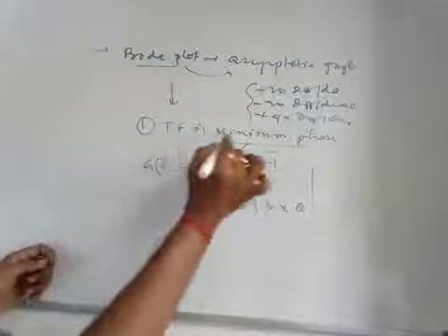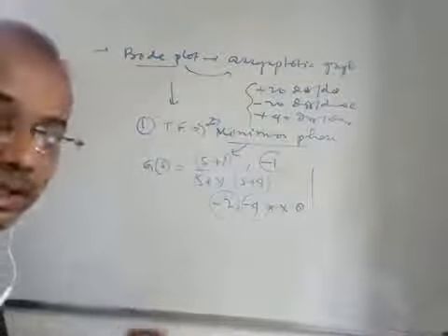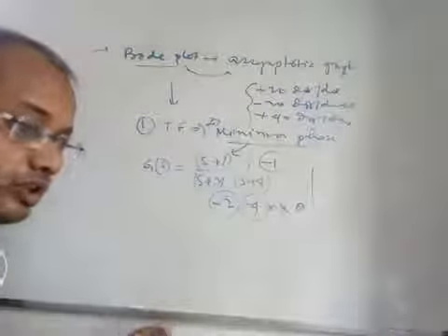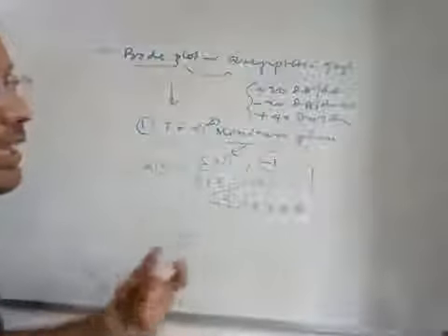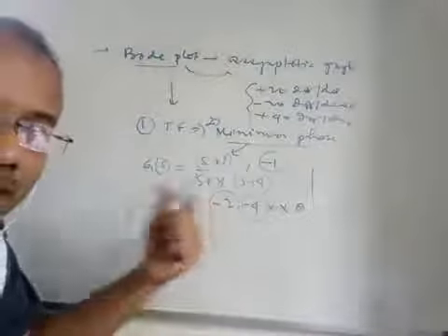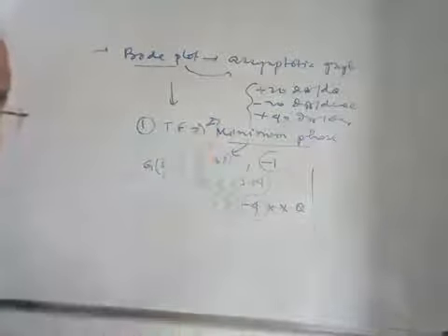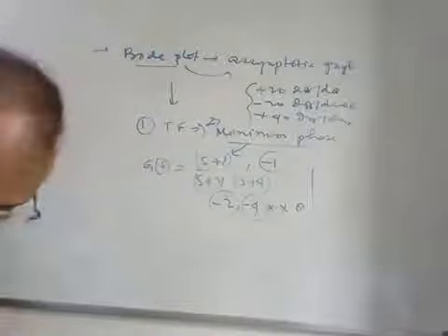For non-minimum phase system, we have to go for Nyquist plot. So Nyquist plot, or polar plot, by using that tool, we can find out the system stability for any kind of system, like minimum phase system and non-minimum phase system. And for Bode plot, we will have to consider the minimum phase system. Why this minimum phase system is very much important, that I will discuss here.